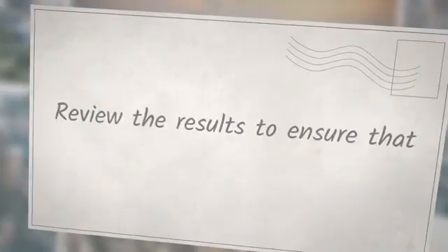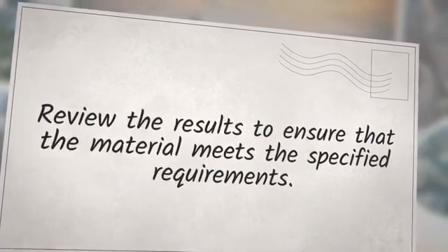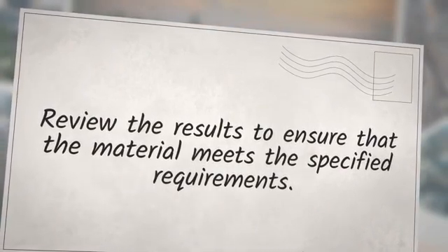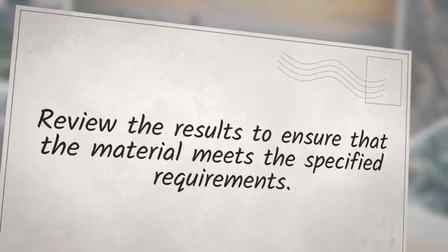This section lists any additional testing or inspection performed on the material, such as corrosion testing or impact testing. Review the results to ensure that the material meets the specified requirements.